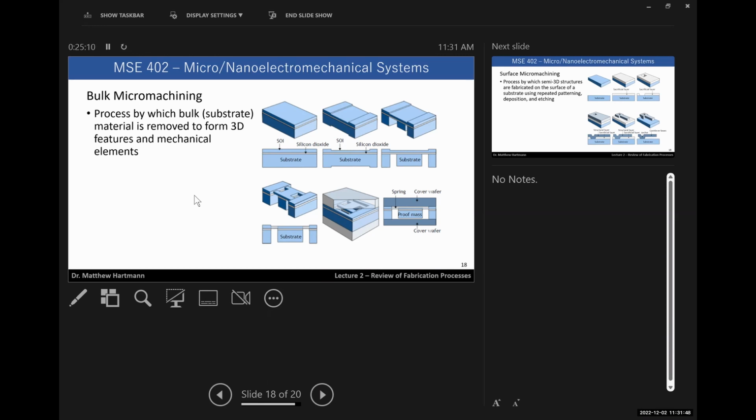So you start off with something like a silicon, the SOI, silicon on insulator wafer. You do patterning and etching to remove some portions of the wafer, both on the top side and on the back side. You do further etching and processing to effectively release your proof mass from the bulk of the bottom substrate. Further etching puts effectively these mechanical springs here and here. These little sections of silicon are nothing more than a spring.